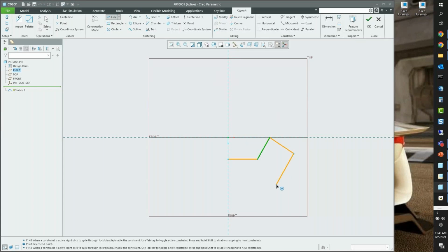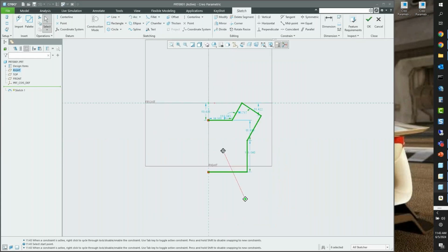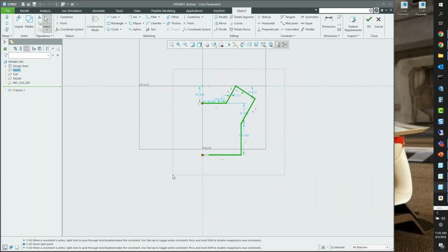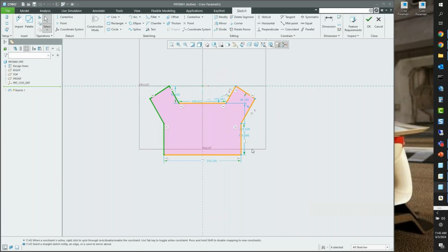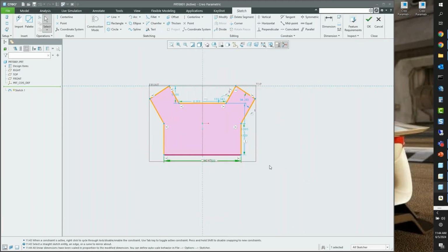So we'll do a sketch that in the past, had you done this and started modifying the dimensions, you would have gotten in trouble, meaning it would have imploded or crossed each other, or maybe wouldn't do anything. But now if I take that first dimension, before I actually make any other change, take a dimension I want to drive and say, hey, maybe it's going into a plastic model car. It's going to be 1.5 inches, right?